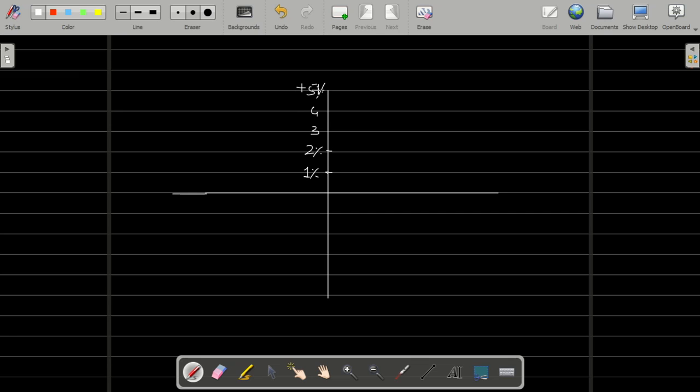I told you already regulation should be less than plus minus 5%. So minus 1%, minus 2, minus 3, minus 4, minus 5%. It does not go above this. Clear? This side is the lagging power factor load, and this side is the leading power factor.